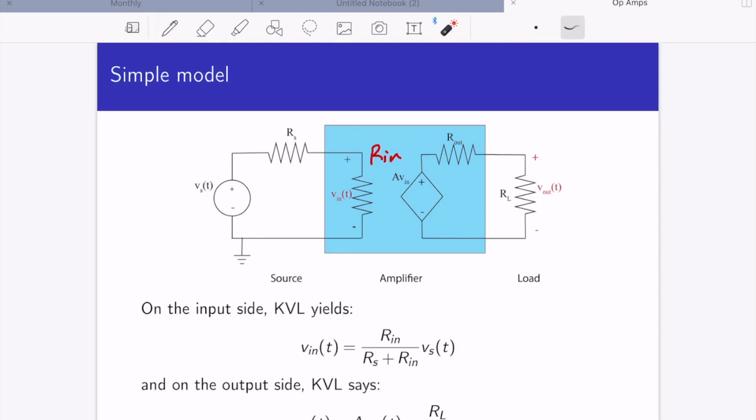Let's go over that again: minus Vs plus I Rs plus I Rn equal to 0. When we solve for Vn in terms of Vs, we end up with an equation for our voltage divider. We actually derived this equation earlier, but you could readily evaluate it by just using KVL.